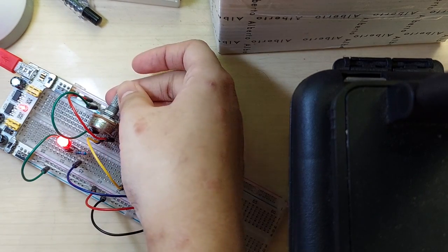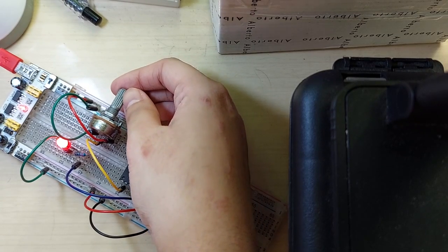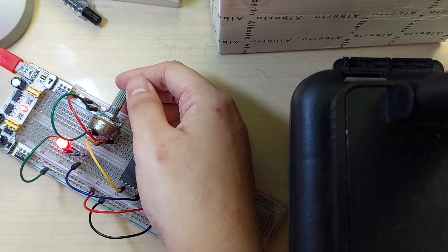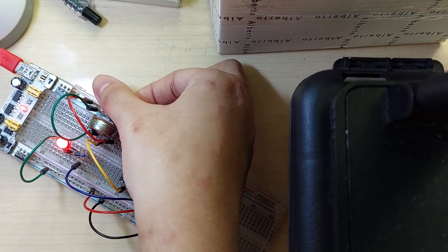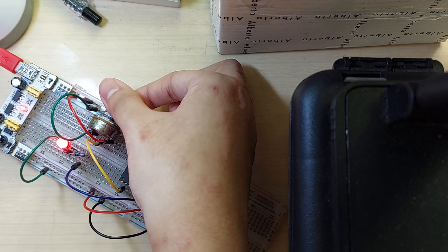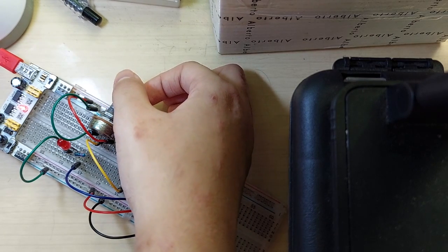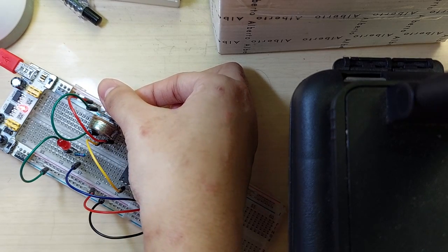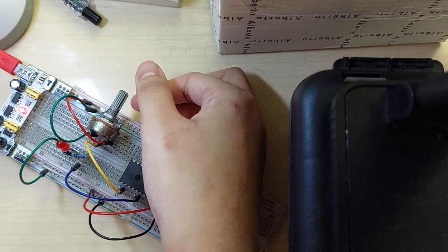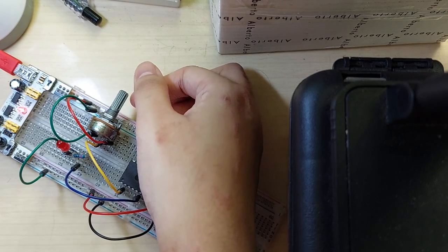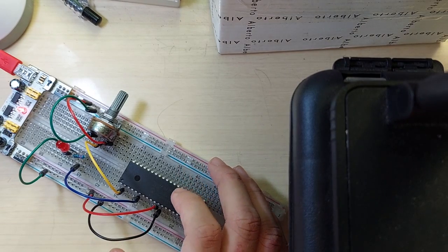Since I cannot turn the knob, this is 0, the LED turned on. If we turn it to the right, the LED turns off. If we turn it further, the LED will still turn off, since the values of the potentiometer,